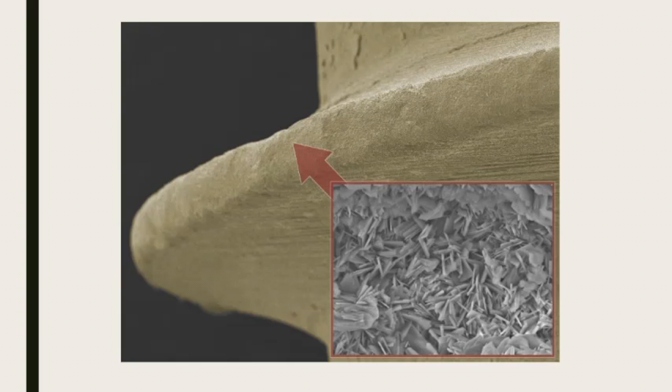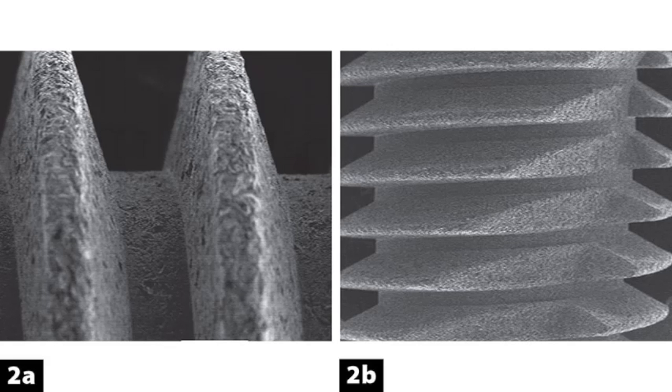Chemical treatments. Chemical reactions can be categorized as specific and non-specific types. If the result of a chemical reaction is a distribution of different functional groups on the surface, then it is a non-specific reaction. Common examples of non-specific reactions include the oxidation of a polyethylene surface by chromic acid and radiofrequency glow discharge, or RFGD. When a surface reaction changes one functional group into another with few side reactions and high yield, it is called a specific chemical reaction. Alkylations and conversion to a siloxane come under this category.